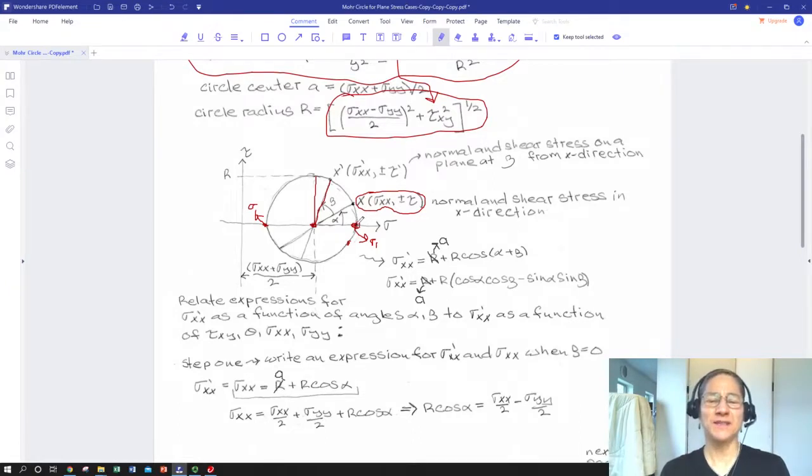So we can basically say, okay, I can evaluate alpha as the inverse tangent of tau divided by sigma xx, and I'll have some relationship of what angle my first principal normal is to my applied load. So this angle alpha is the direction in which it's the x direction effectively.